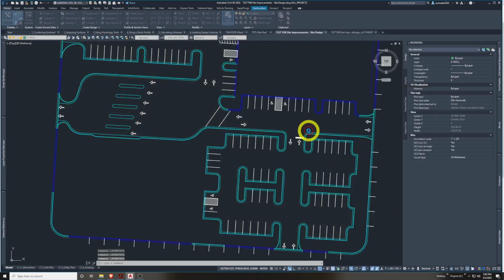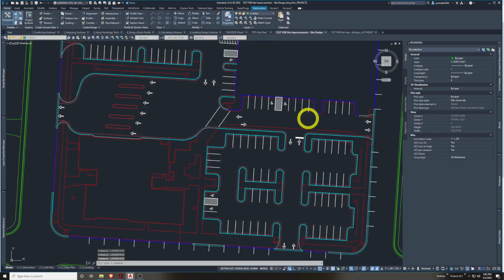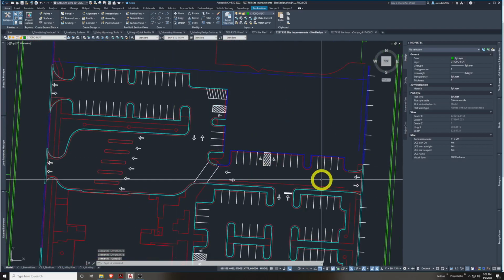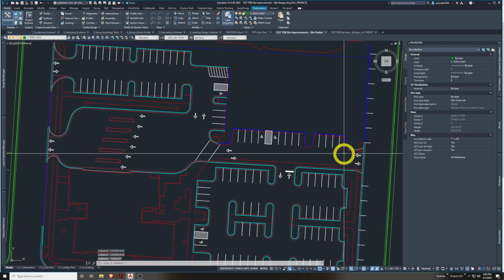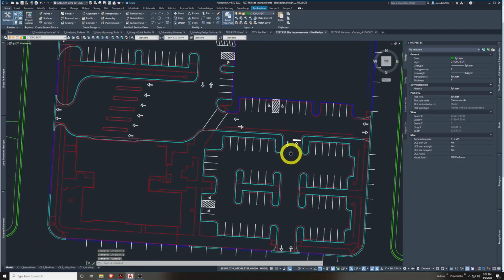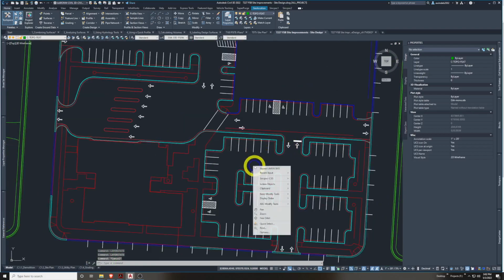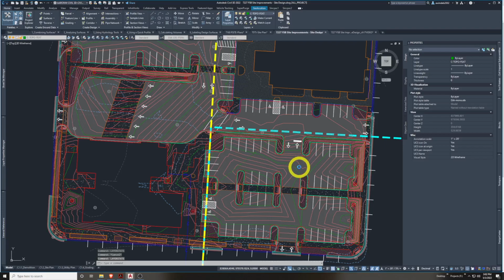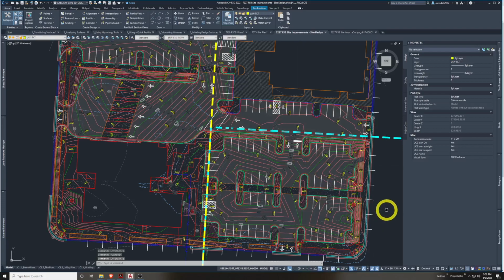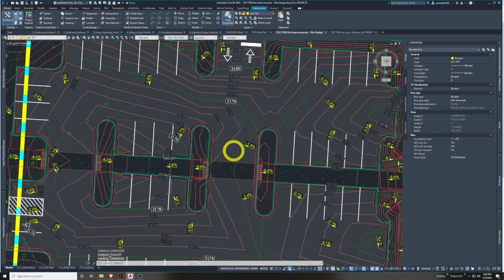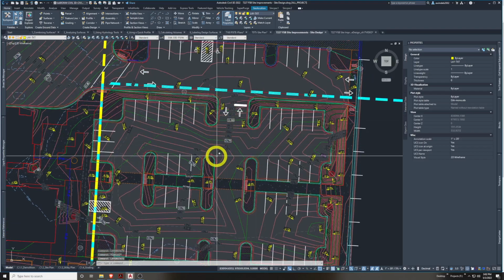we start to make a bunch of feature lines, which I started laying out my parking lot. All these red lines were my feature lines. I started dialing in, drafting, getting the elevations set. Well, first of all, getting them horizontally correct because I based them off these polylines, and then I started grading them out. So towards the end, as I started to build their elevations, they maintain a certain surface form in 3D. Here's their contours and some of their contour labels and stuff.